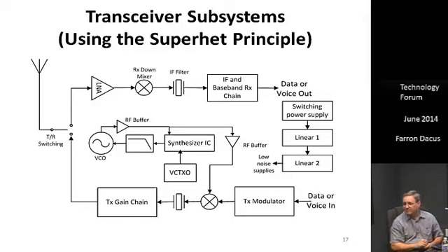Semtech is boasting a transceiver chip that claims to have receive sensitivity on the order of minus 140 dBm. Possibly 150, approaching the theoretical noise floor. Well, how effective can that be? As long as I've been in the game, everybody's been able to design radios which approach the theoretical noise floor within, say, 6 or 7 dB. You can design a receiver that has a 6 dB noise figure.